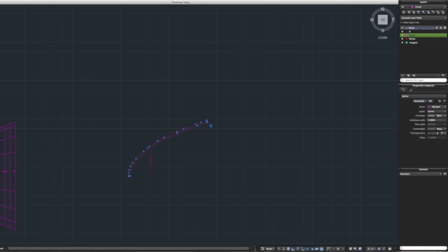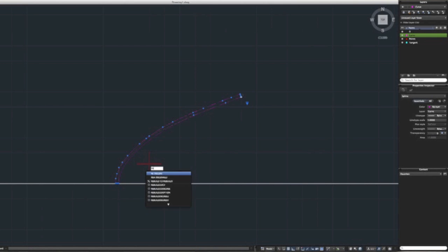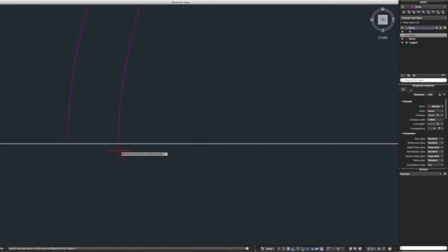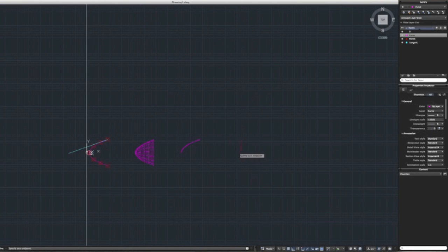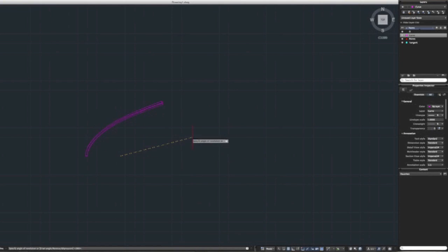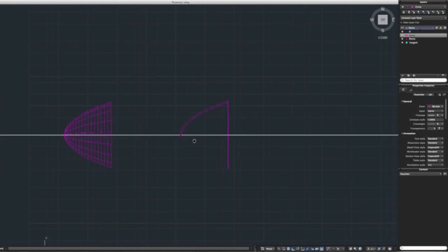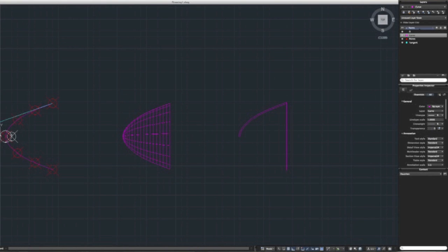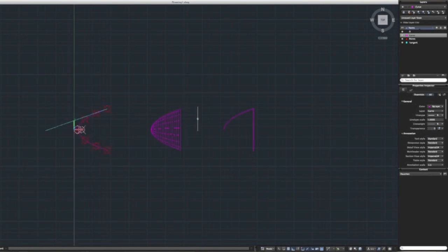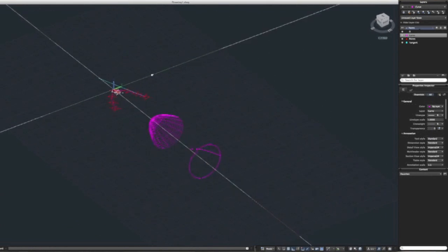Now, how to make that almost perfect cone without edges? We select our object, we select revolve, we go into our axis. Just give it, yeah, about here should be about enough. And now that we've made an axis, we can just turn this around. Just enter because it will already be 360 degrees. Put into a conceptual view, and now you can see it in 3D.